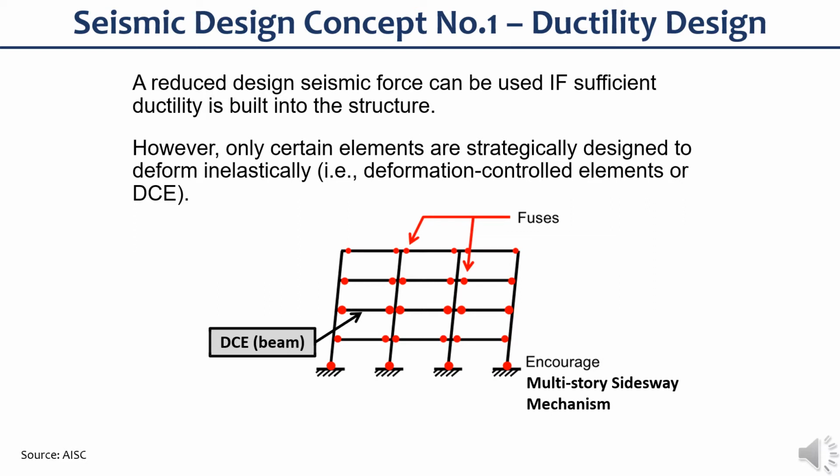In this concept, we need to, number one, provide yielding elements to control overall force. It's basically to make sure the fuses are ductile. And second, to protect the non-yielding elements, that is, to estimate the maximum force from the fuses.